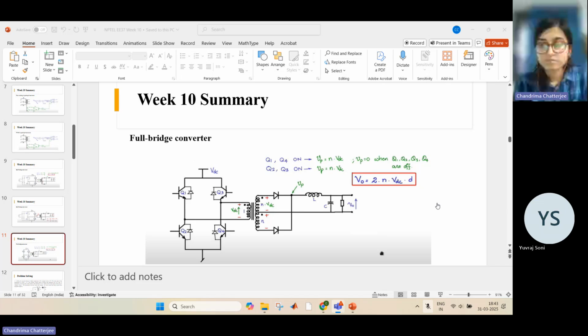Because we can neglect the ripples, as in the question they have asked to neglect the ripple. So if you just assume square wave type waveforms, in this interval when Q1 is on, the D1 diode carries the total load current. After that, when the inductor is freewheeling, the load current is split and each diode carries half the load current. And then when Q2 is on, the diode D2 carries the total load current.